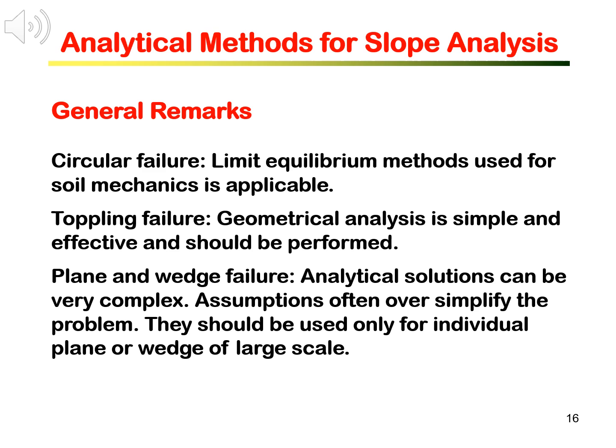We have learned that we can use limit equilibrium methods with method of slices developed in soil mechanics for circular failure of rock masses that behaves like soils, such as completely weathered, crushed, very highly fractured, and very weak rocks.